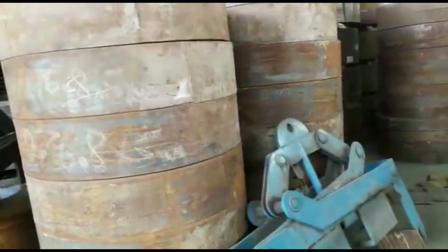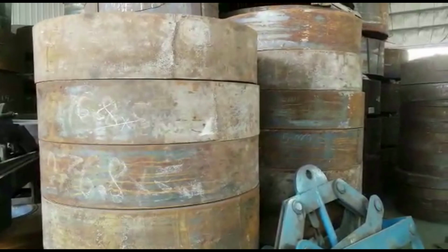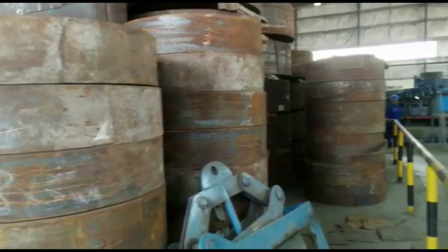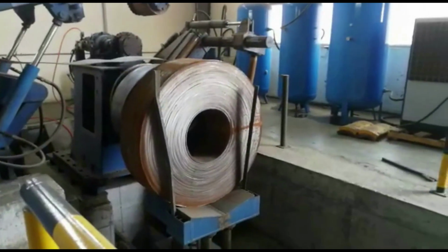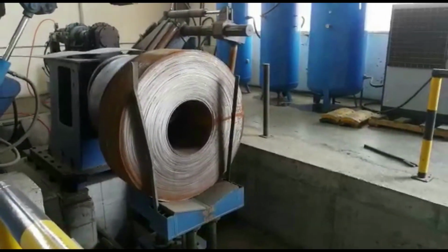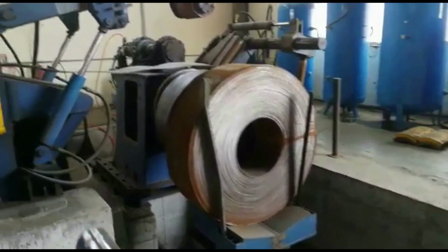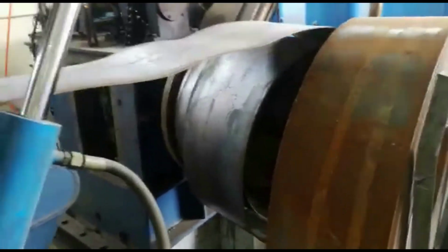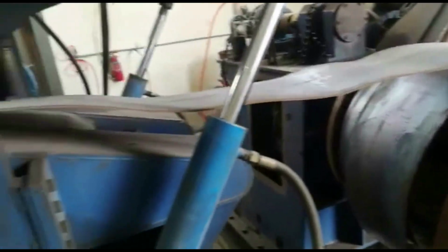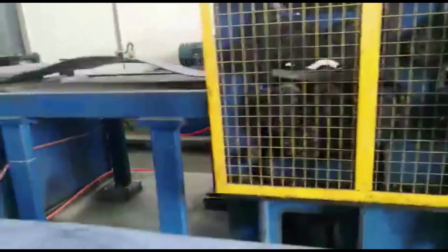Steel pipe production. The video shows the mild steel flatbar coils stacked on each other. Each coil is of different size for producing different pipe and tube sizes. MS coils are the raw materials used for making pipes and tubes. The MS coil is transported to the loading car using an overhead crane. The loading car carries the coil and feeds into the uncoiler machine, which uncoils the coil into flatbar.